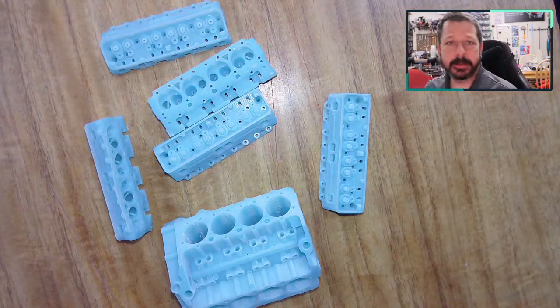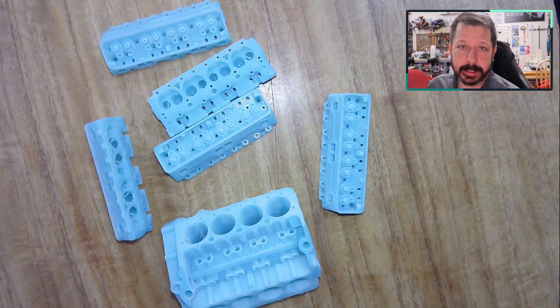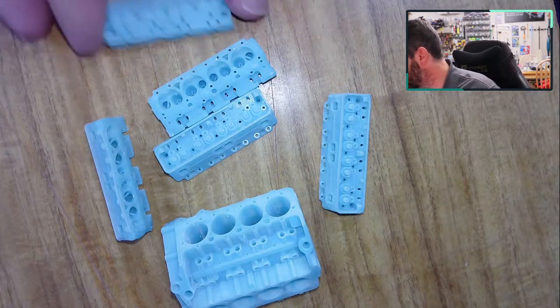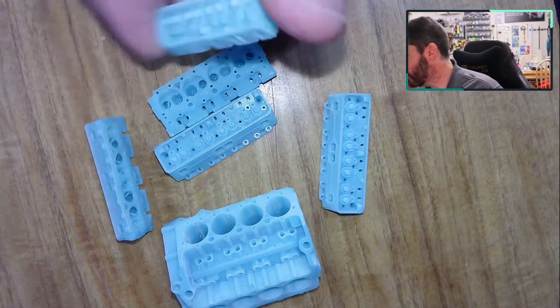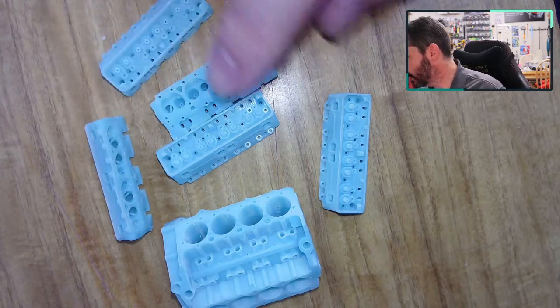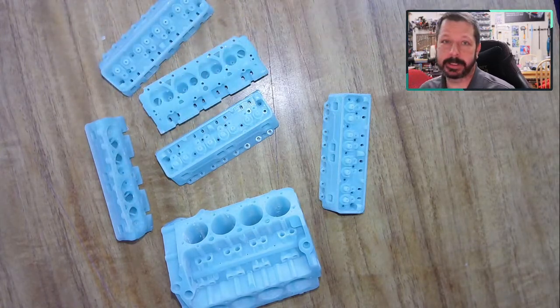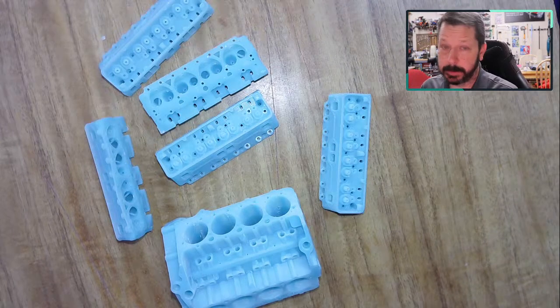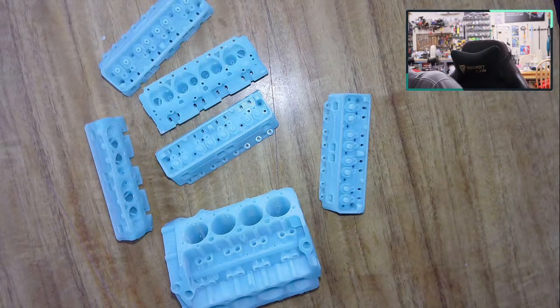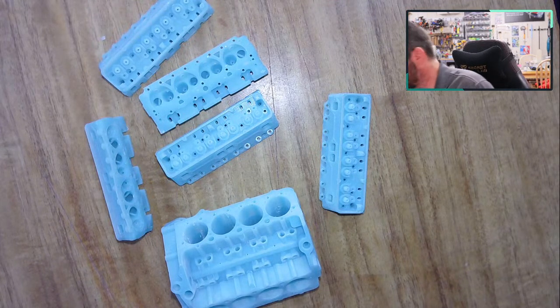With resin, you do have to be careful about the dust that you're generating when you sand, because breathing the dust would be harmful. Touching these after they're cured is not a problem. Touching the liquid resin can irritate your skin, and repeated exposure will potentially give you chemical burns. And so you can kind of see, you get some really good details.